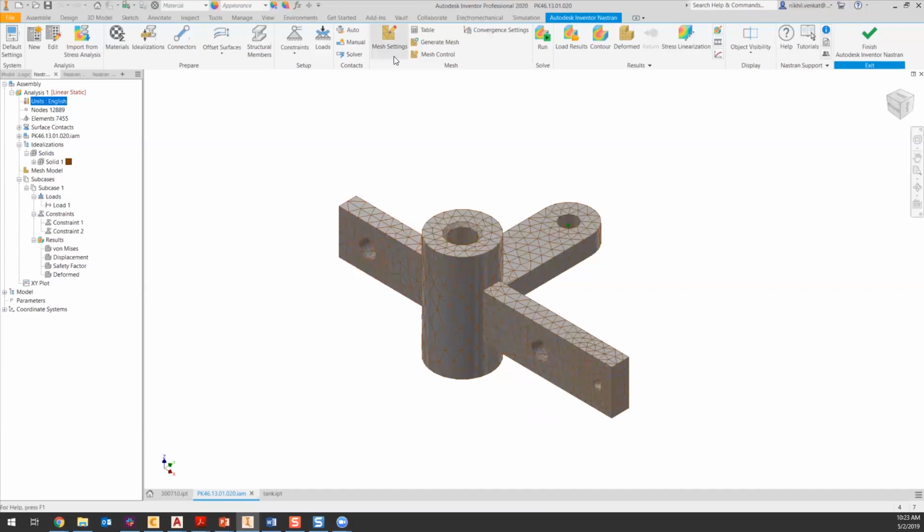It's got nothing to do with the total size of the element itself, but the local refinement is going to deal with those areas of highest stress. And again, it's important to remember here that it is highest stress and not highest displacement. Cool. Hopefully that answers that. Nikhil, can you go into the results of this and show where it actually shows the convergence stuff? Sure.